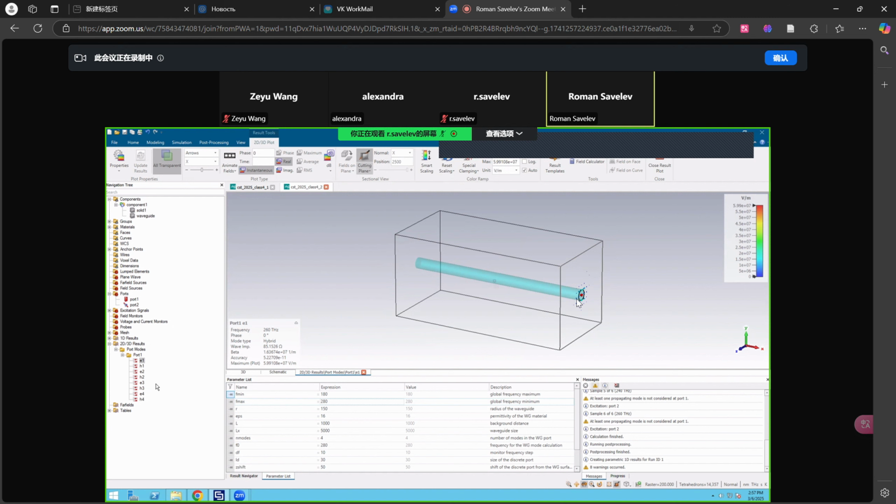We forgot an important thing. We forgot to change boundary conditions. The boundary should actually be open, all of the boundaries, because now we're considering the source that is in infinite space. So if you have some different boundaries, please change all boundaries to open.